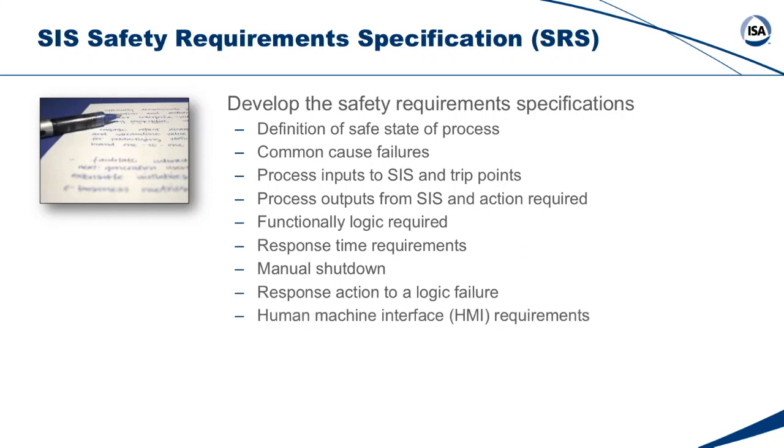What, if any, kind of human-machine interface are you going to have? Many safety systems do not have a standalone interface. They communicate to the control system, and the operators build up the screens they want there. But it's important to have proper displays. ISA does have a new standard on this and is writing additional technical reports. And there's some really good books on high-performance human-machine interfaces.